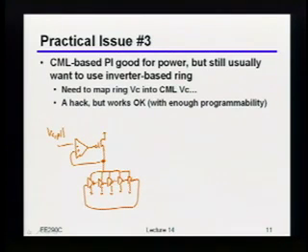Okay, and then, as we said before, to do the phase interpolation, I actually have to grab multiple of those phases at the output, right? So let's say I just grab these two just for the sake of example. And obviously there are really muxes there that decide which ones you grab, but I'm just drawing this for simplicity now, okay? So now, unfortunately, what I have to do is take those outputs and then feed them into this Maneatis-based phase interpolator. And I'll just draw that as these two triangle things with the controlled weight over here, okay?